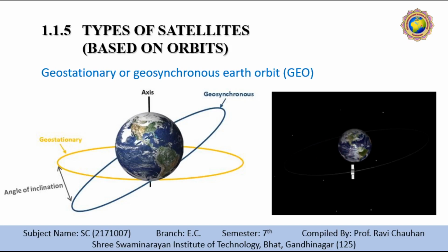The biggest problem for voice and also data communication is the high latency, as without any handovers, the signal has to travel at least 72,000 kilometers. Due to the large footprint, either frequencies cannot be reused or the GEO satellite needs special antennas focusing on a smaller footprint. Transferring a GEO into orbit is very expensive. So there are some pros and cons we have discussed. Let's go ahead.